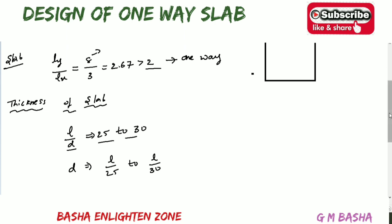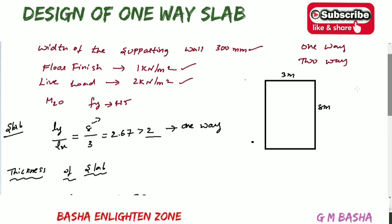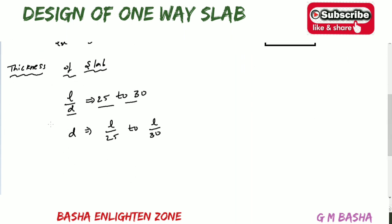So what is the L value? The L value is clearly given, that is 3 meters. Taking it in terms of mm, it is 3000 by 25 to 3000 by 30. It works out to 120 and 100, so the depth will be in the range of 120 to 100 mm.